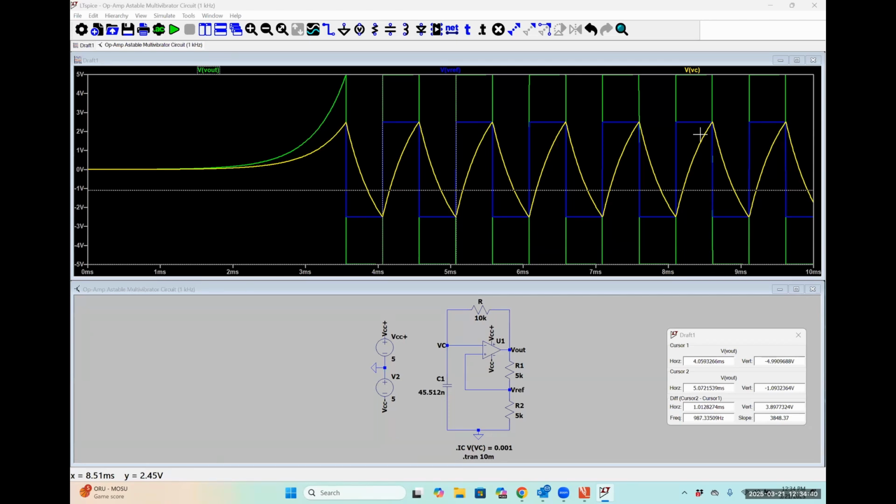But effectively, this circuit to me is pretty darn interesting because it literally does not have an input. This is a situation that I talked about in class where our feedback factor times our open loop gain is intentionally set to be equal to 1 so that we get oscillations with effectively no input voltage whatsoever. Now, because I'm using ideal components, I did have to give my system a little bit of a push.